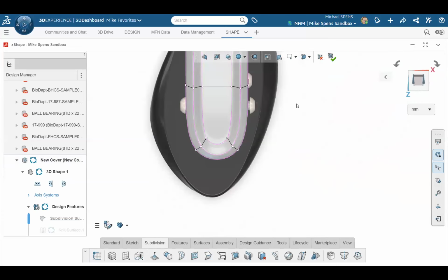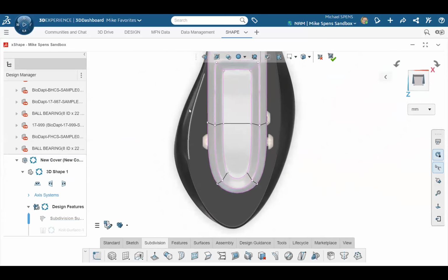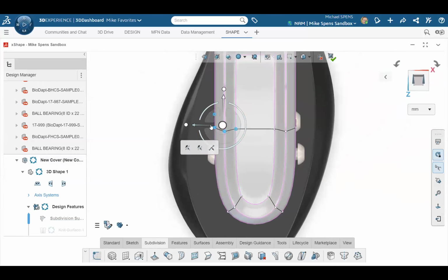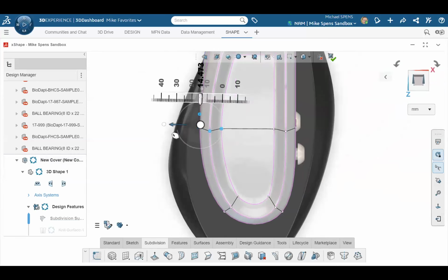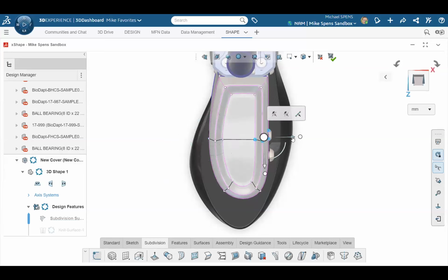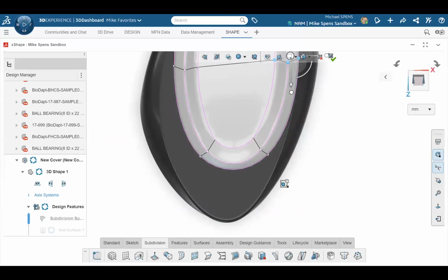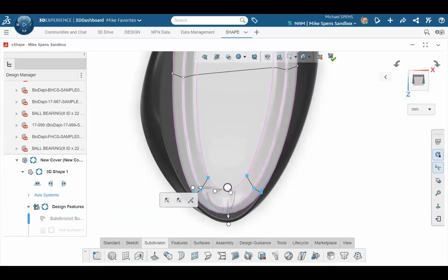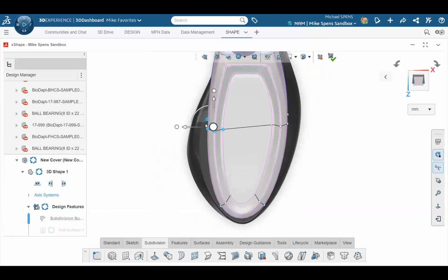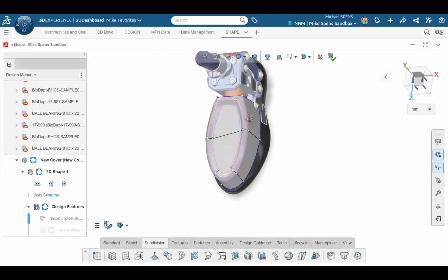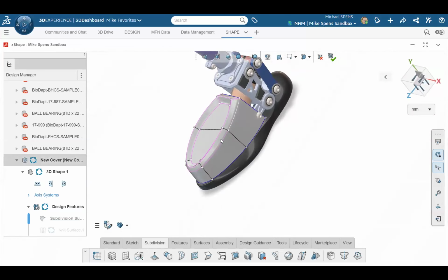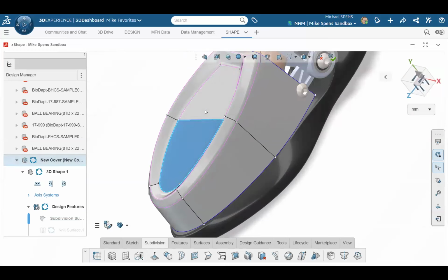What does that model look like if you bring it into SolidWorks at this stage? It's like an imported body. So it's like an imported STL file. Not STL. No, it's a surface body. So it's a watertight solid. So you could shell, you can add extrusions, you can do all that kind of stuff that you would do with any other imported shape, but the control remains in this environment. And you're still referenced to that. If you don't break the reference, you can still go back and have all the latitude that you're showing right now.